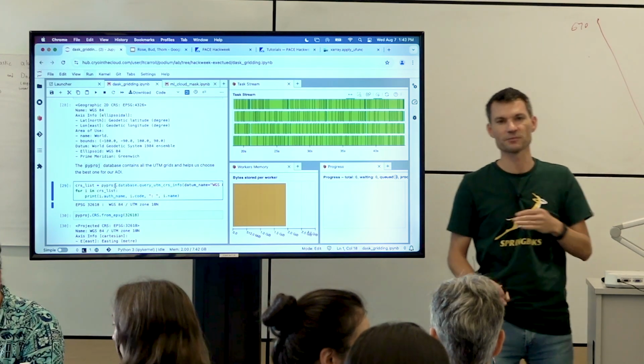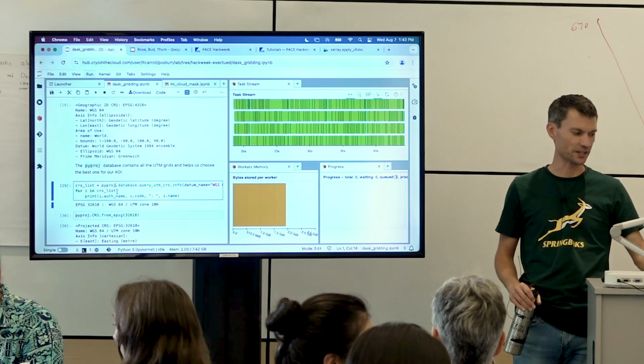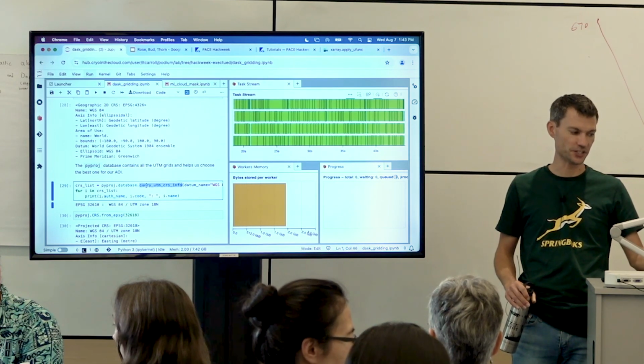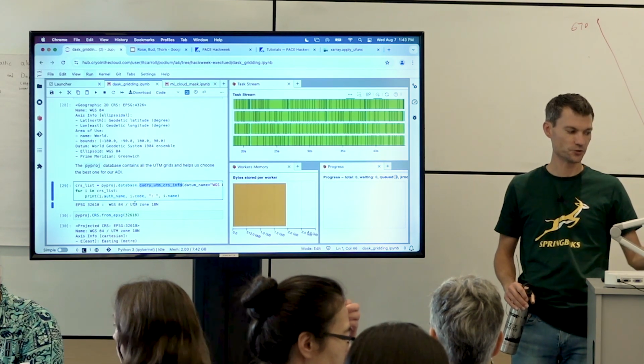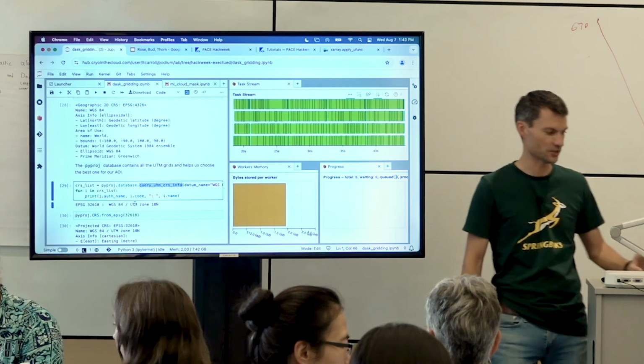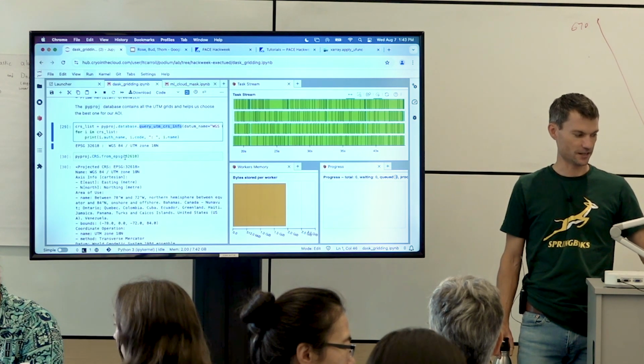They're all numbered, like up through 20, I don't know. So PyProj will tell you. You can look it up. You can give it your area of interest and say query the UTM coordinate reference systems, and it says use UTM zone 18 north. Great, OK. I'm going to project to UTM zone 18 north. That also has an EPSG code, et cetera.